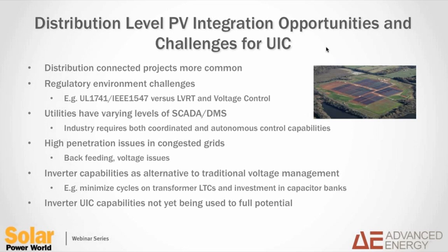Traditional voltage management comes in the form of cap banks, load tap changers, inline voltage regulators, etc. But there may be ways to leverage inverter technology to minimize cycles on those types of voltage regulation devices and really provide a service, not just solve the problem that PV delivers, but be a solution to other problems that the utility is dealing with.